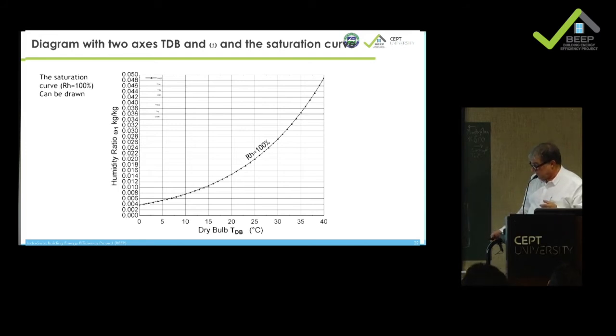Typically, if you weighed air completely saturated at 35 degrees, you would have 1 kg and 36 grams, the mass of air plus the mass of water in vapor form. Now remember what we showed before, that the relative humidity goes with the partial pressure.